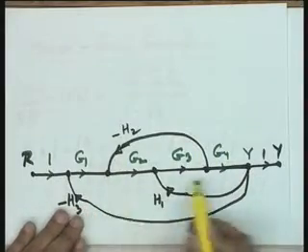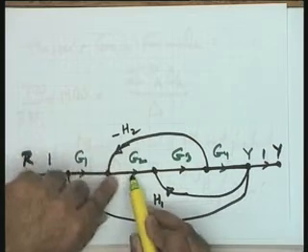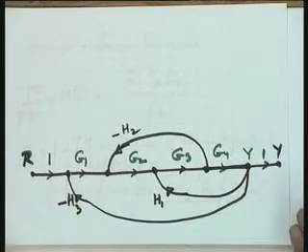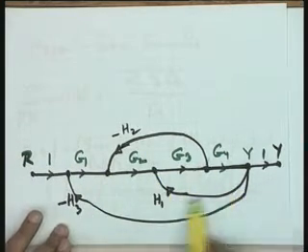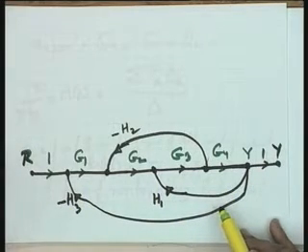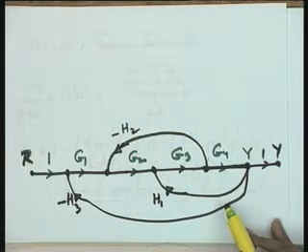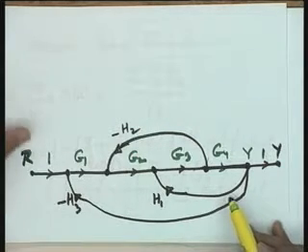Some of you may take this as a loop again, but in this particular case, how many independent loops are there? 1, 2 and 3, because in all these 3 loops there is at least a node or a branch which is different. Those loops will be referred to as independent loops.